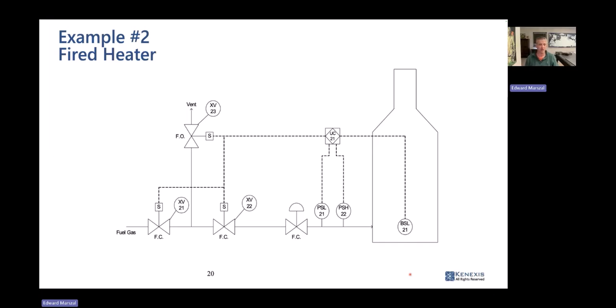in all of the ISA training classes on functional safety, you're going to run into voting arrangements that we call M out of N. So 1 out of 2, 2 out of 2. For 1 out of 2, M is 1, N is 2. N, the last number, is how many devices in total there are in the system.